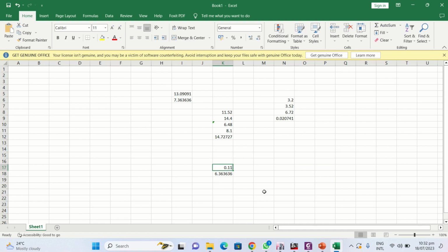If you use number 4 bar, for example, the area of one leg for number 4 bar is 0.2. So we will need 3.5 legs. It means we will need 4 legs, right? So the area for the 4 legs is 4 into 0.2, which will become 0.8, and then you have to divide this area of the number of legs that you will provide by the area of reinforcement required, which is 0.7.